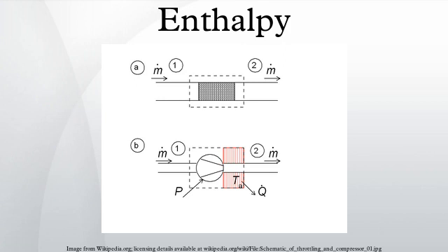Note that the previous expression holds true only if the kinetic energy flow rate is conserved between system inlet and outlet. Otherwise, it has to be included in the enthalpy balance. During steady-state operation of a device, the average dU/dt may be set equal to 0. This yields a useful expression for the average power generation for these devices in the absence of chemical reactions, where the angle brackets denote time averages.